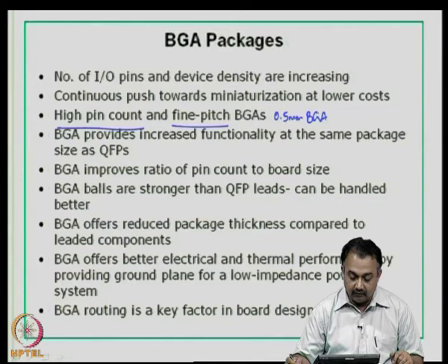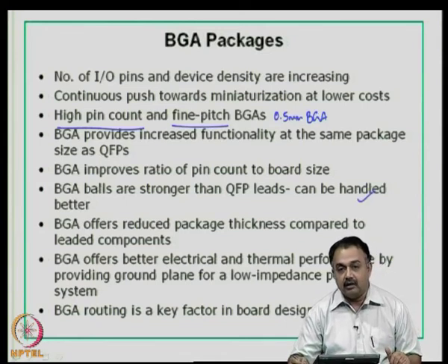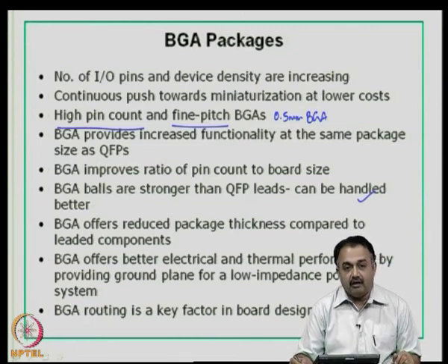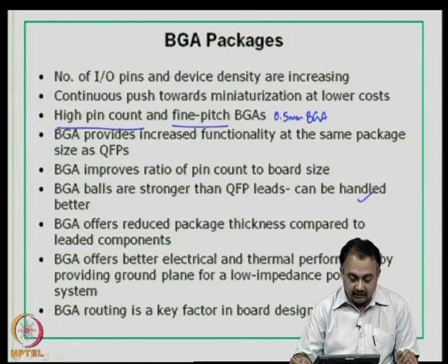which is not possible actually with QFPs. BGA solder balls or interconnects are stronger than the QFP leads, and therefore, could be handled in a better way in terms of assembly and testing. BGA offers reduced package thickness compared to leaded components, which is a fact.